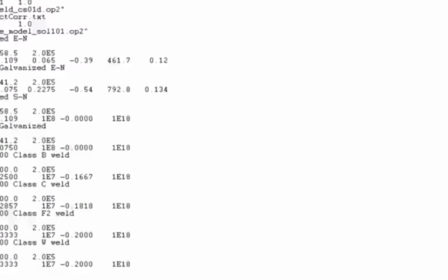And the only thing I've done in this control file that's different is I've added something here to reduce the output to just one element, 40631, using something called the fset3 option. And then I've changed log level to 2. Now what that's going to do is write a lot more detailed information out, but for just the one element, 40631. So if I run that job,